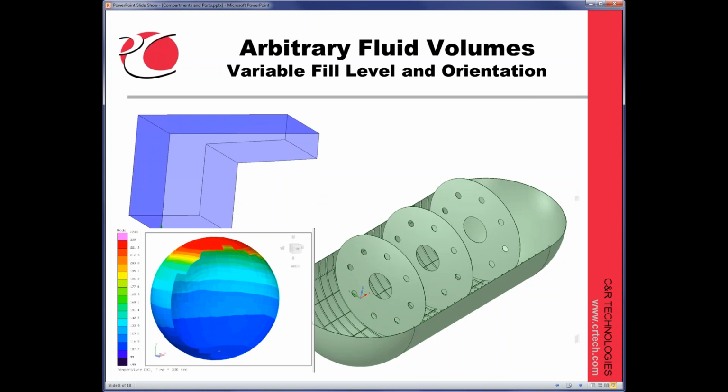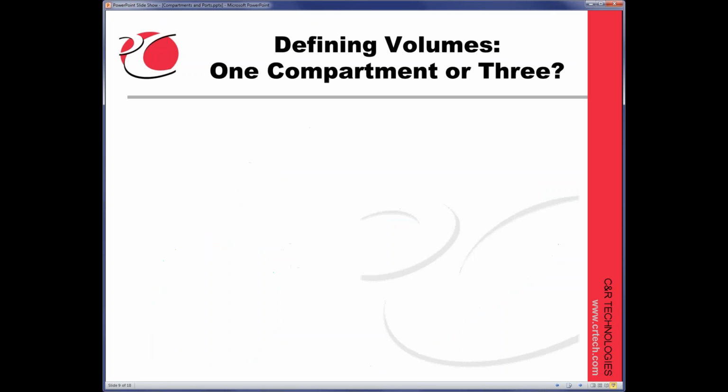And this is only about a 5-minute transient here, so it's a fairly quick drain. But as I'll show you, the system is meant to be run for hours long if you need it. Okay, so this is the kind of volumes you have. Everywhere you have the gravity direction, you have fill levels, and anything you've defined in here will be intersected by this liquid vapor plane and either considered to be wet or dry as a result of that.